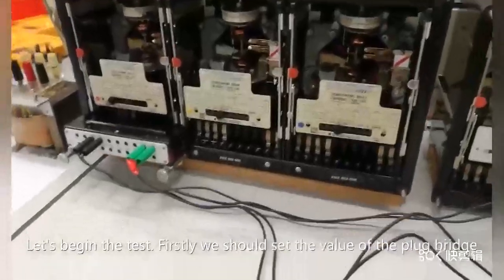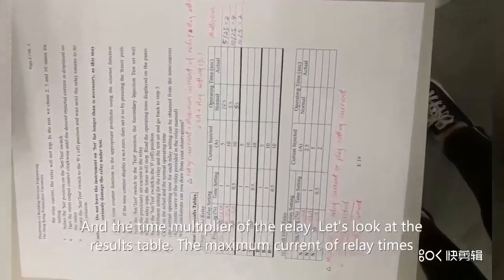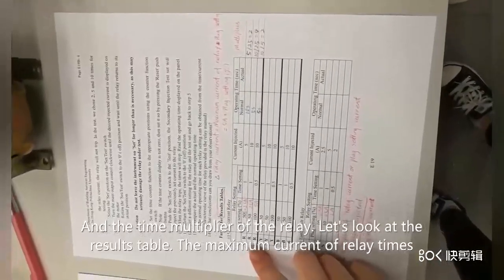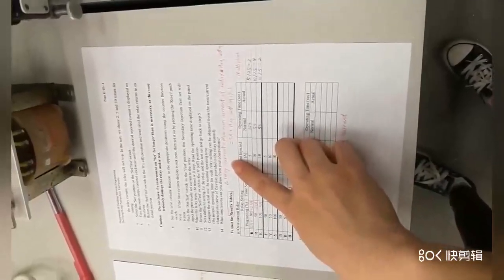Then we should set the value of the plug setting and the time multiplier of the relay. And look at the results table. The maximum current of the relay times the plug setting is equal to the relay current.